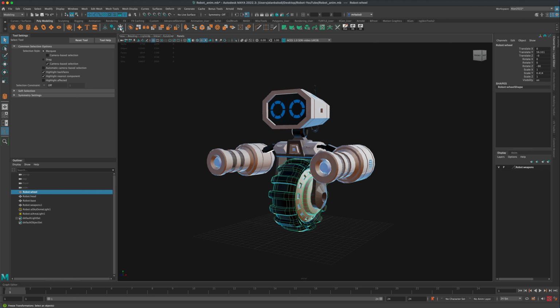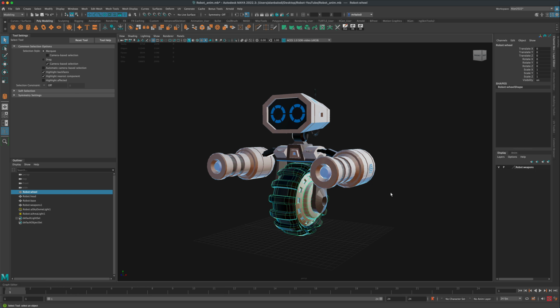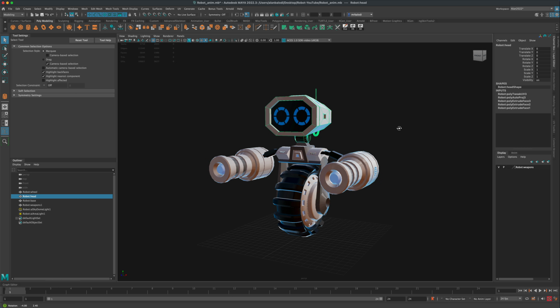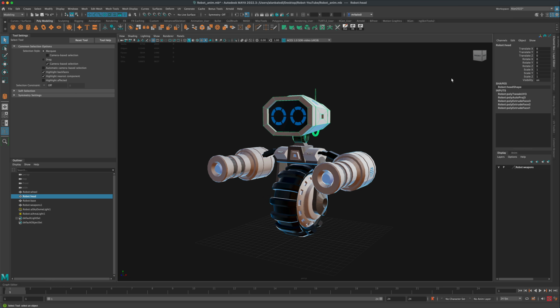So once you click on it, you can see that all the values are now set to 0. And honestly, before you create any animation, it's really important that your rotation and translate values are 0, because then during the animation, you know that 0 is your default state, right? So you can always come back to the same position.